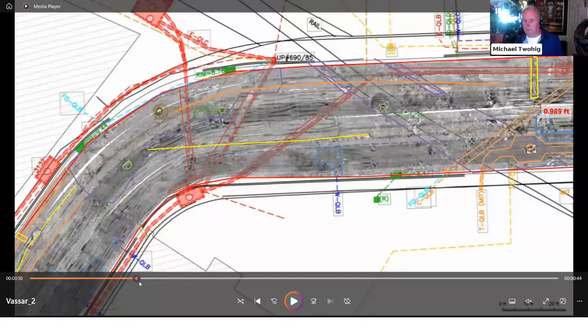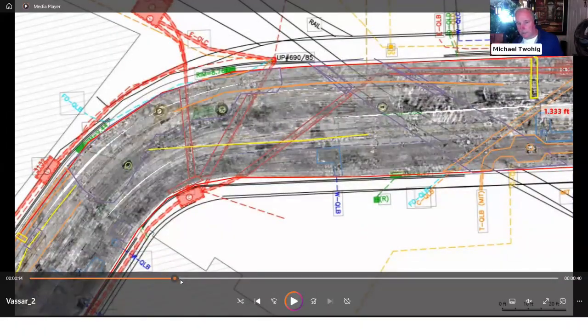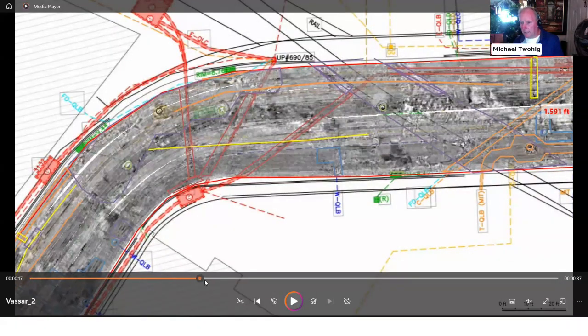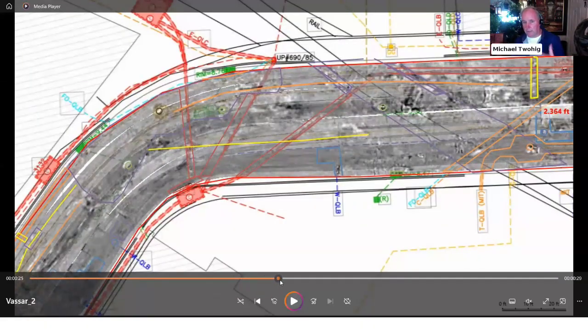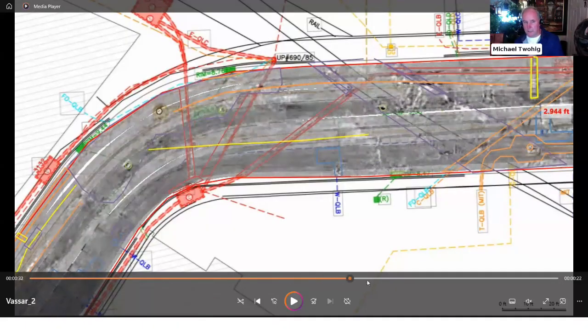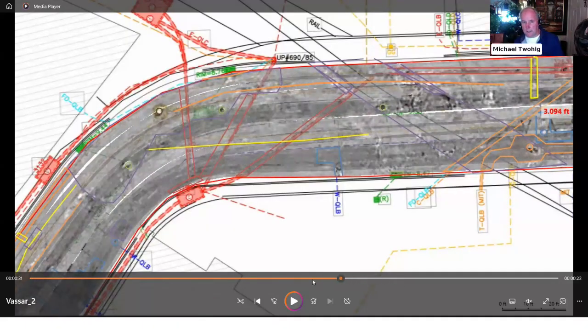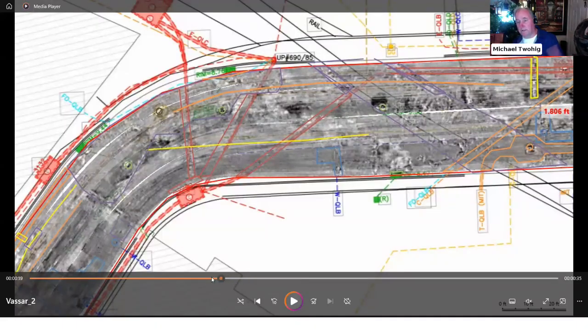To doing a mile of this type of street, which is as tough a street as you're ever going to find, would have been about 3 weeks of quality level B with your traditional crew with a pipe locator and push cart GPR. But the GPR collection would have been done in a single day. So this would have been Mitch Liddell and myself or one of the other techs driving this, getting the entire coverage curb to curb. In some areas, we're actually able to do the sidewalks because they were big enough and they had some ramps.